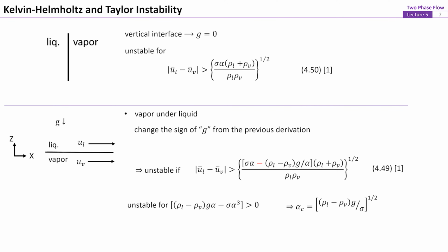In this case, the fluid with higher density is above a fluid with lower density. The gravity tends to make the interface more unstable, whereas surface tension tends to stabilize the interface. Note that the right side of equation 49 also does not have a minimum value. This means that if disturbances of all wavelengths are present, some of them will amplify.